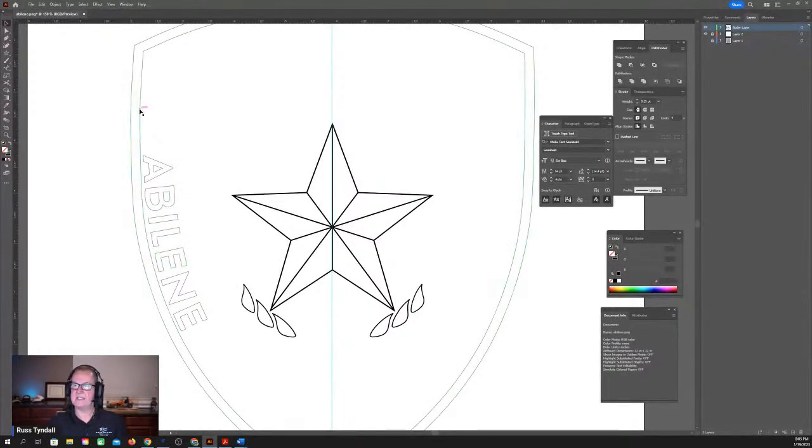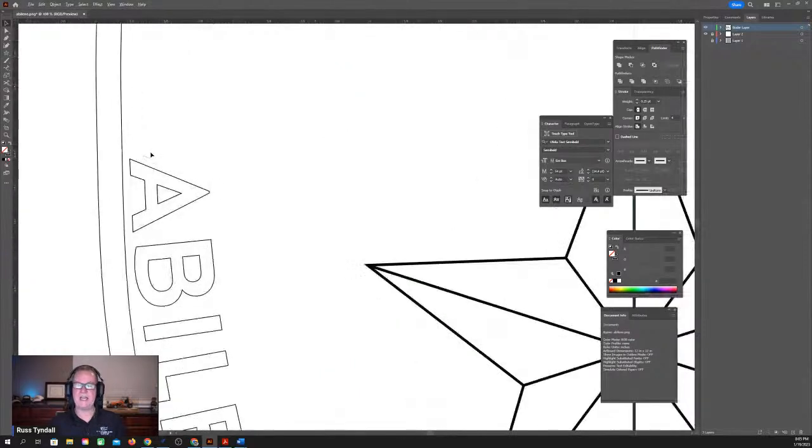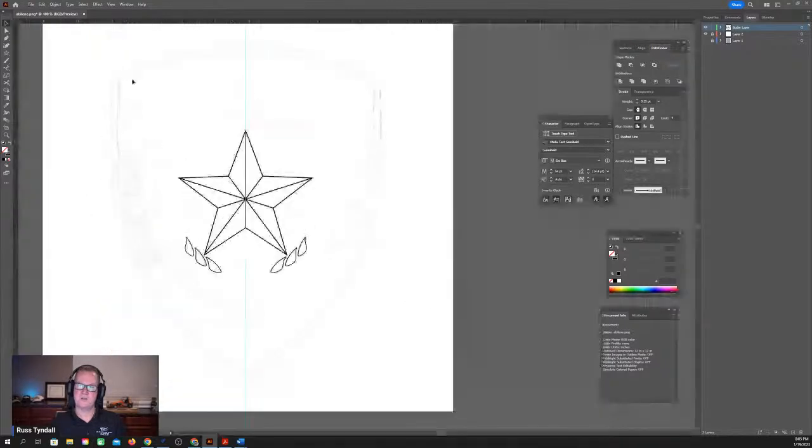And in the case of a CNC machine, if you're running a pocket toolpath and you decide to pocket this border out with, say, an 1/8 inch end mill, it just needs to know the border to stick within. And the same thing with the VCarve. If you choose to use a V-bit, like a 90-degree V-bit or a 120-degree V-bit, I would recommend something to that size.